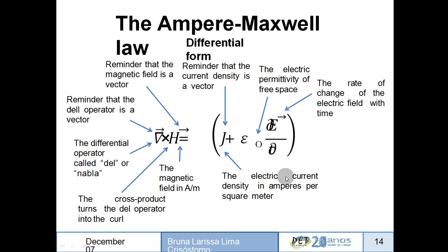And this is the differential form. This we have already described. By using the Stokes theorem, we can prove that del cross H, the curl of the magnetic field strength, will be equal to J plus epsilon 0 into del E by del T. Now J is the conduction current density, epsilon 0 is the dielectric constant of free space, and del E by del T shows the time varying field, the rate of change of electric field strength or electric field intensity. So this is the equation.